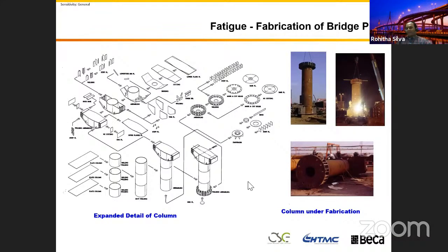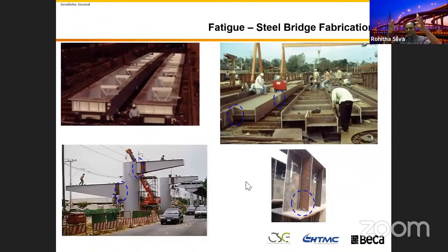I could remember by heart the fatigue section. If I give you an example, one of the most critical in the fatigue design in the AASHTO is this welding joint in here. This bottom flange and this stiffener, this is category F. If I give you the number, those days back in the AASHTO design standard it is 7 kips. 7 kips, in the sense you have to multiply this one by 1000. 7,000 divided by 142 is the MPa. Roughly, 7,000 divided by 142 is about 50 MPa.